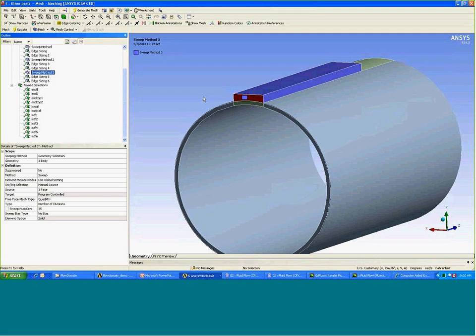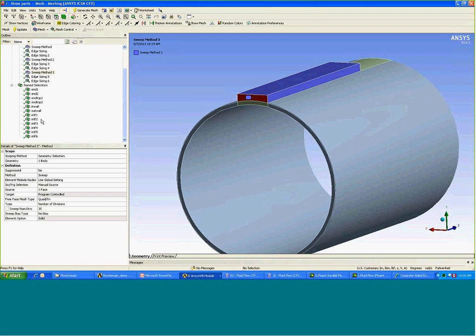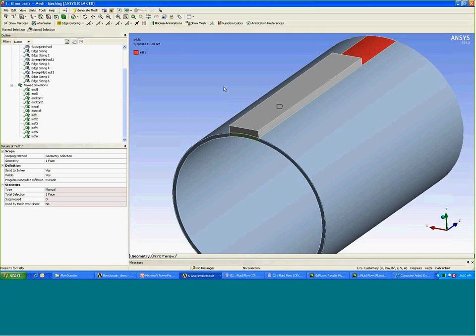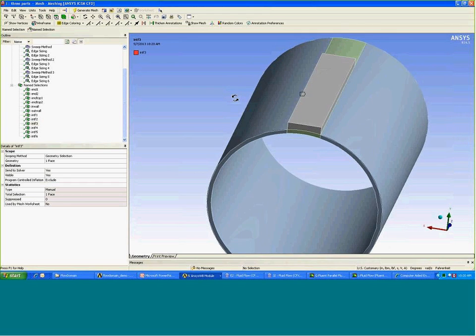In addition to the boundary surfaces that I selected, similar to what we did previously with N1, N2, in-wall and out-wall, in this case I created 6 more, which are the 6 surfaces where these 3 parts come into contact. Each contact surface has 2 sides, so I named them interface 1, 2, 3, 4, 5, 6.